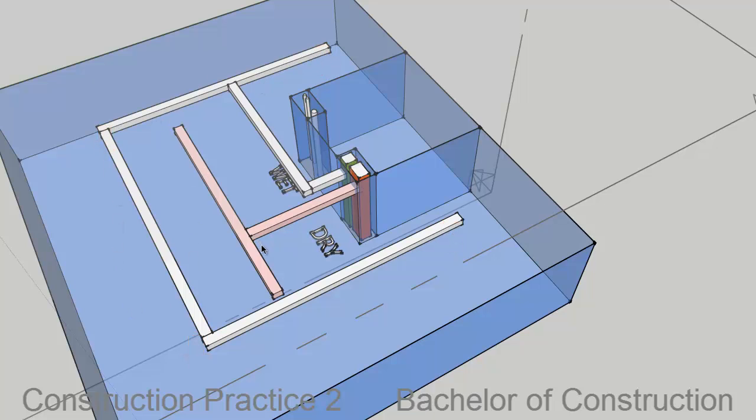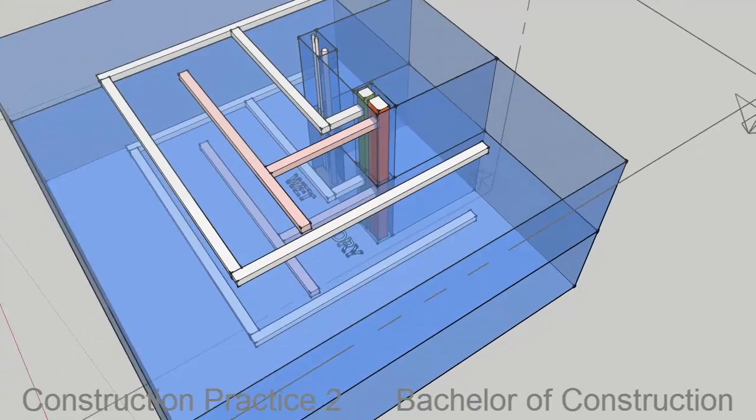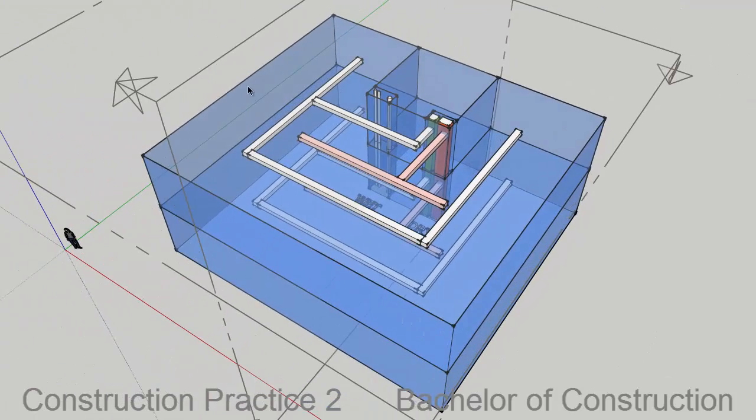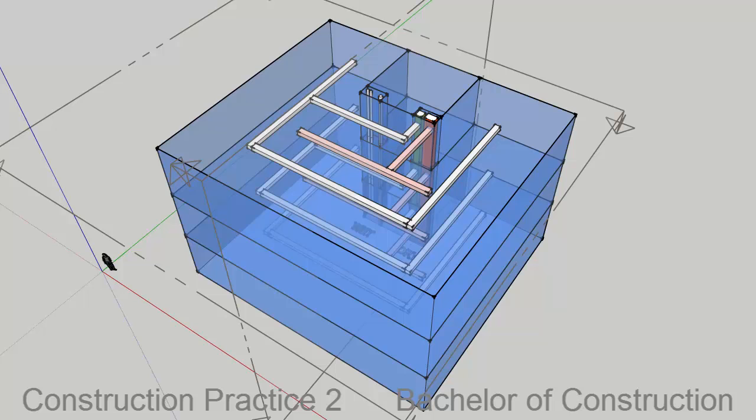And we've also got a return air duct. So on every level, the air gets extracted from the floor and taken out through this vertical duct, in the same way that this vertical duct here, the supply duct, provides air to every level. And so what we essentially have is like a main artery running up and down the building with branches out at every level. Essentially we end up duplicating that type of layout on every level.